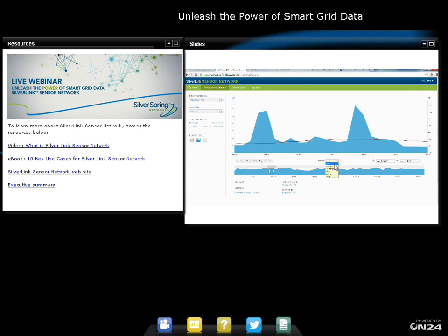You have to dial in the granularity of the data into a more granular basis. So now I'm showing you 1 minute interval. So 1 minute interval data, at that granularity, you can see a lot more stuff happening, right? You can tell exactly what these peaks are, and you can see that there are additional patterns that occur throughout the day on a very regular basis. Now, this may still be pretty confusing to the human eye, but when you run it through a computer-trained algorithm that has lots of information about what different appliances look like when they use energy, it can actually tell what the different appliances that make up this usage profile are.